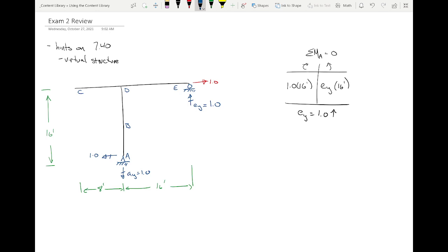Now, the other hint I mentioned on the homework assignment is that your coordinate systems should be pointing towards D. What I was saying about that is, typically what you don't want to do is define a coordinate system in the middle of the member, because if you're cutting sections and you're cutting that piece out, you need to know the internal shears and axial forces there. Typically what you want to do is define your coordinate systems at the end, because if I start here, there's nothing down, there's nothing past it. Does that make sense? Now, what is the internal moment in this member?